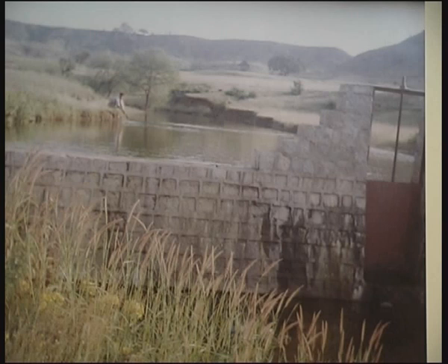Again, when one upstream recharge structure of a check dam is resulting in base flows in the stream and it is flowing down to a lower area in the stream, there is no need to construct one more check dam on the downstream side for the purpose of recharge. Already base flows are there in the stream and there is no need for recharge in such a case.